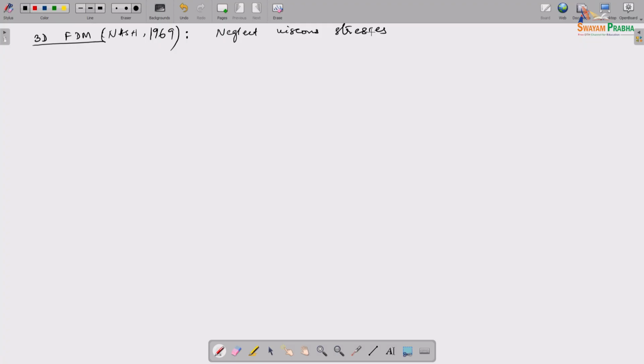I think it's time now to relook at how we looked at the turbulent boundary layer. In the turbulent boundary layer there were several layers. There's a viscous sublayer, and the dissipation layer. So these were layers that we looked at. When we say neglect viscous stresses, I guess we're going to neglect that little height of the boundary layer which is close to the wall in order to do that. Let's see how we will do that.